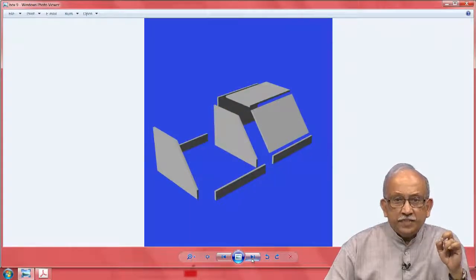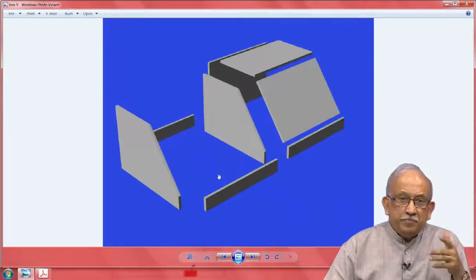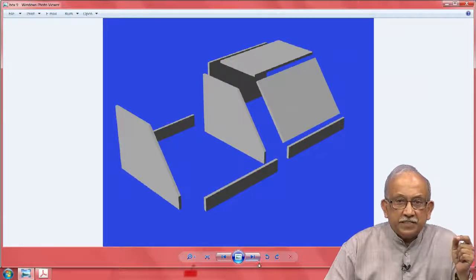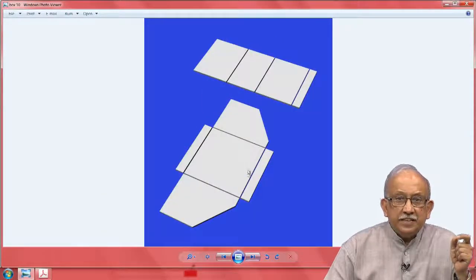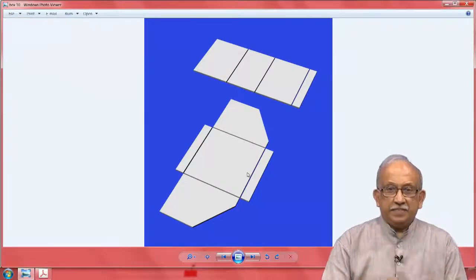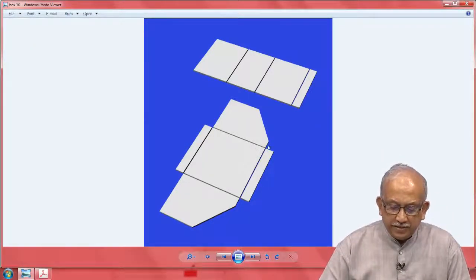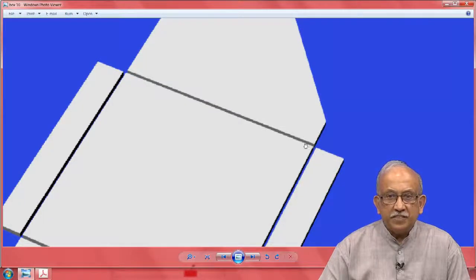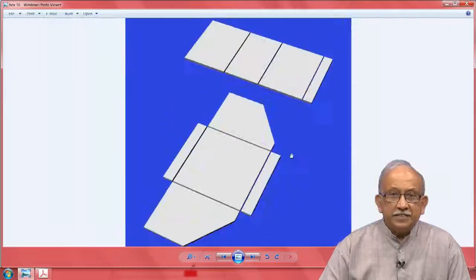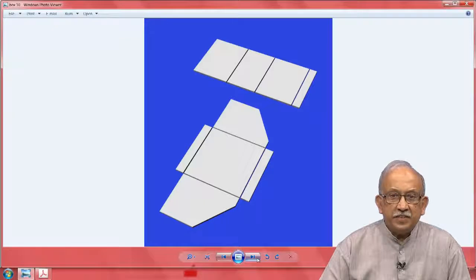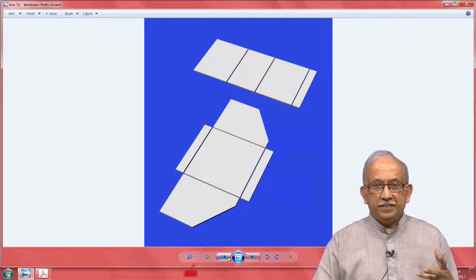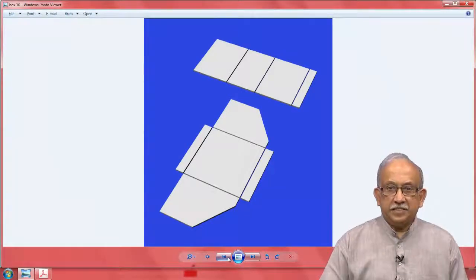So generally what is done here is we try to find out the actual panels of what fits where inside. This is where all the thickness compensation and all will be there, and then eventually try to lay them out flat. You see there is a small gap here, can you see here? In the corner there is a small gap, this is not meeting here, this is not meeting here. So here now first time we end up with trying to work around or make proper blank or sheet metal calculations.